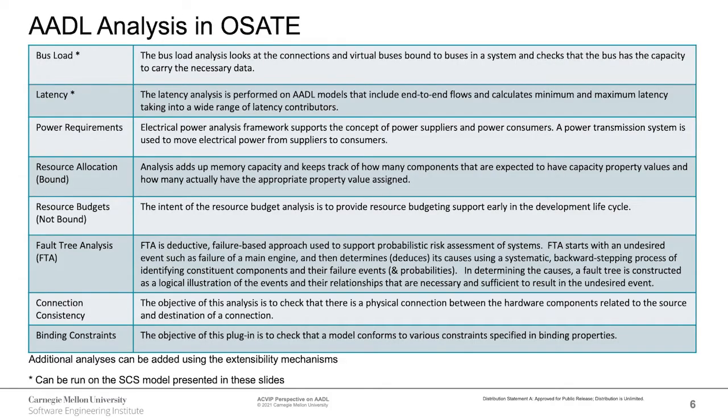As you can see on this slide, there's a variety of AADL analyses available right out of the box in OSATE tool. These analyses can be run on the same model to verify that no device is overloaded and sufficient power is supplied to components. In-depth description of each analysis can also be found in the Help section of OSATE tool.